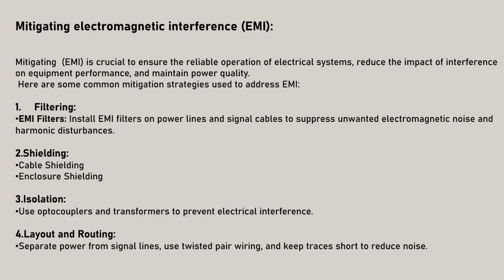Isolation. Optical isolation. Use optocouplers or fiber optic communication to isolate sensitive circuits from noise-prone environments and prevent electrical interference. Transformer isolation. Employ transformers to provide electrical isolation between circuits and eliminate common mode noise.